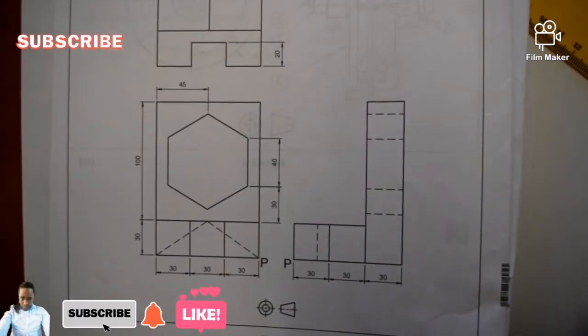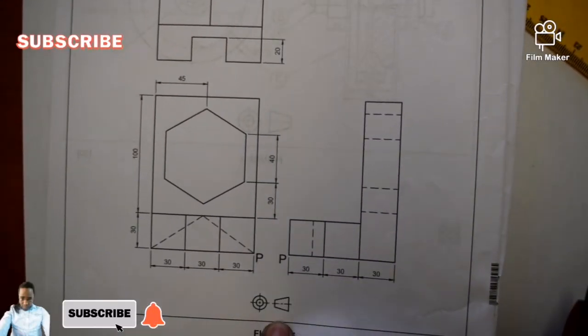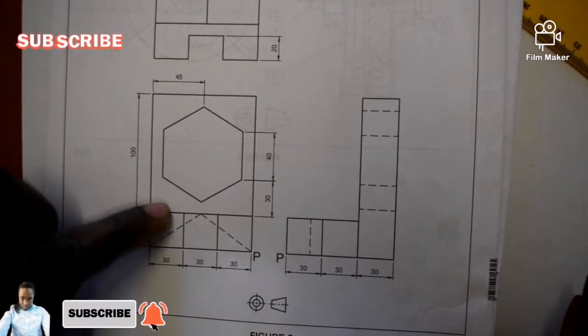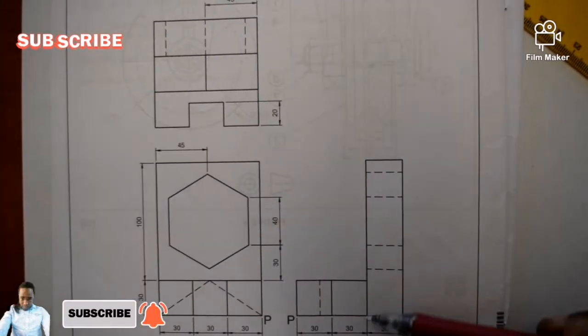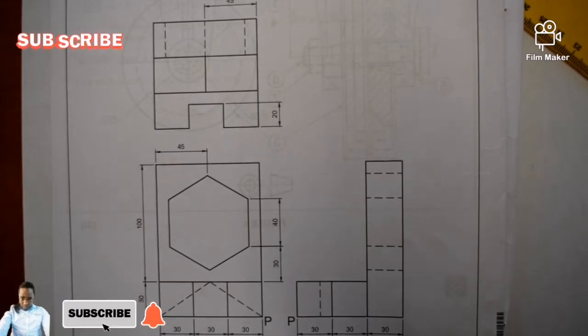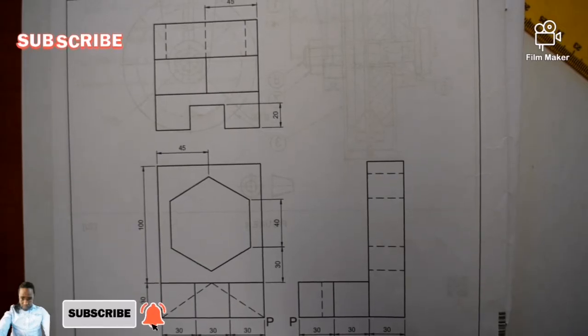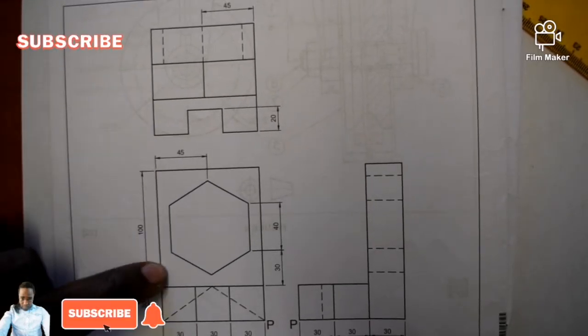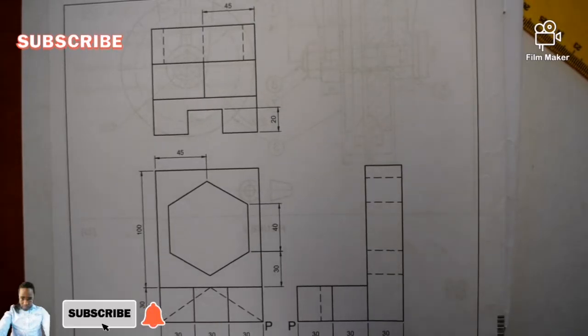This is it. Then after that, I bring back my views. We are given 3 views here, with the projection symbol. Let us analyze them. This is going to be my front view, this is going to be my top view, this is going to be my right view. You must understand orthographic projection: how do you analyze your views if they are given in third angle orthographic projection? The top is this one, the front is this one, the right is this one. We do not talk about the left view in third angle orthographic projection.